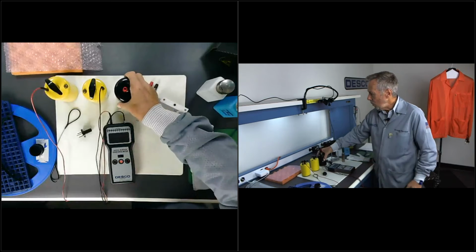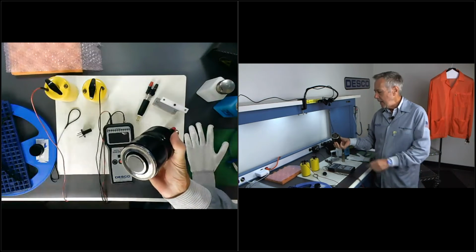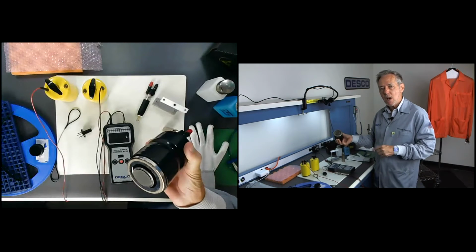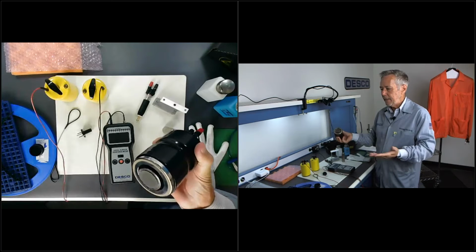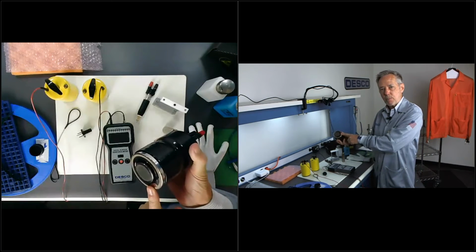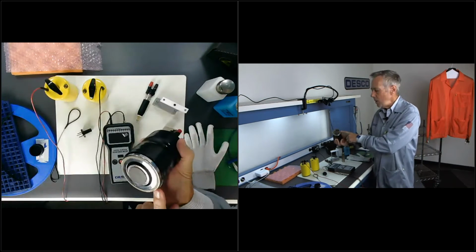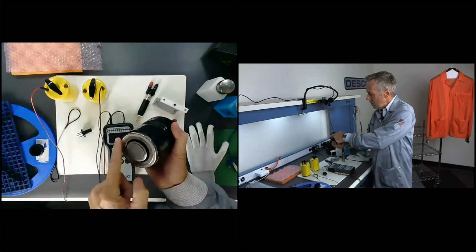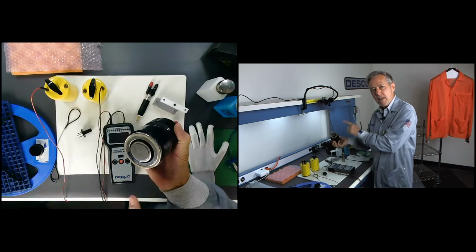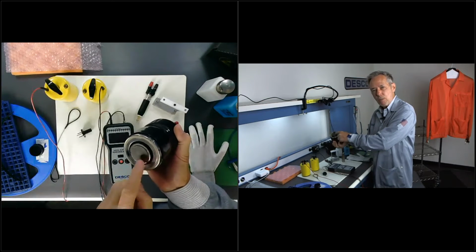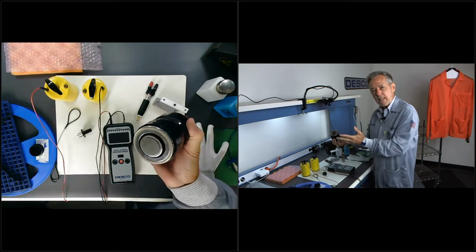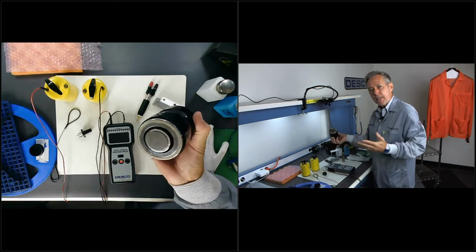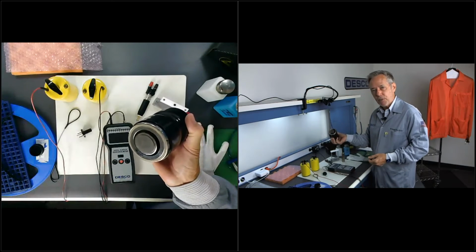I also have what we call a concentric ring probe. And this tester or probe is used when I'm testing surface resistance on planar materials. Basically anything flat and large enough that I can fit this probe on. So this is like having two probes in one. As you can see, there's an inner test point here, and there's an outer test ring here. Now what this does is measure the resistance between these 2 points. And so this is basically what we call measuring ohms per square. Now it just so happens this is the distance, but that could be an inch, that could be 5 inches, that could be a foot, whatever it is.